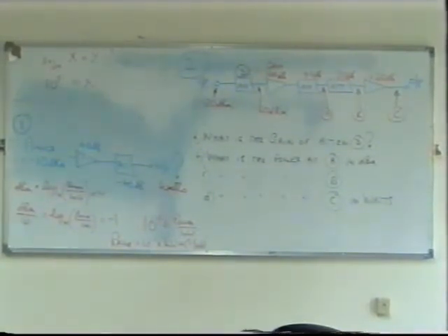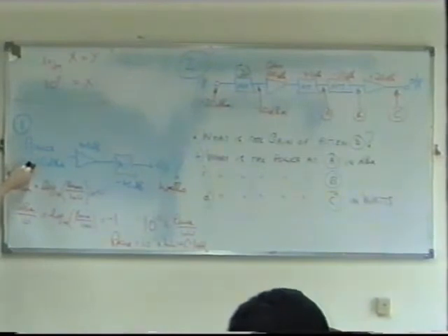No, this is a measurement of power. This is not a power ratio, this is a measurement of power. I meant, what does it mean when you see the minus sign in front of a dBm? The definition here is just to say the dB is the ratio of power. Yes. What I'm saying here, though, is in dBm, what does the minus sign tell you?